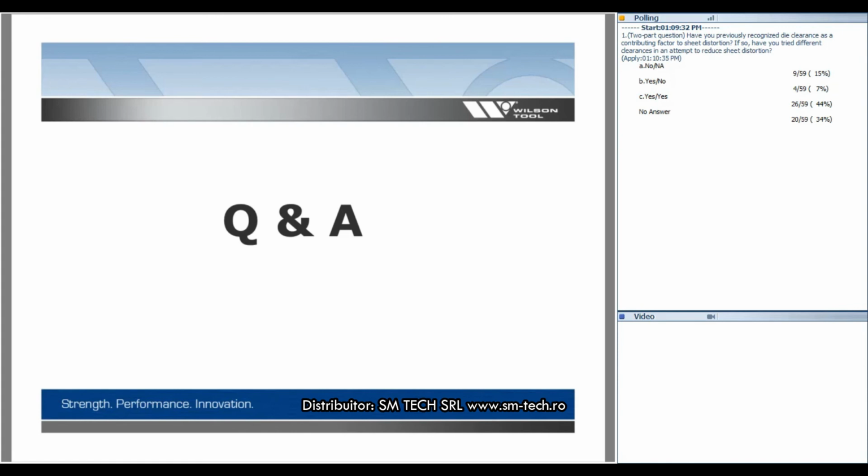In a Trumpf, the question is how many forms am I allowed to create in a Trumpf machine where I can take advantage of that stripper plate. Most forming tools don't use a stripper plate in the Trumpf. The controller might not even allow us to attempt to use it. But there are certainly cases where it can work. For the most part, Trumpf is using the stripper plate for piercing, and the P&F is a forming machine.